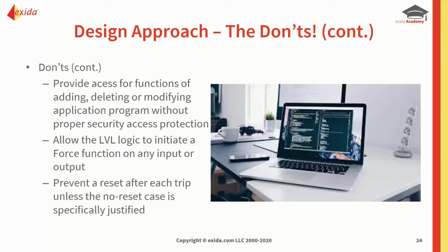Also, we don't want to provide access for functions of adding, deleting, or modifying without proper security. So this means that the engineering workstation for the SIS should be locked away when it's not required. It shouldn't be permanently connected to the SIS. And not only that, it should have password protection to make sure that only somebody who is competent and responsible is able to make any changes to the application logic.